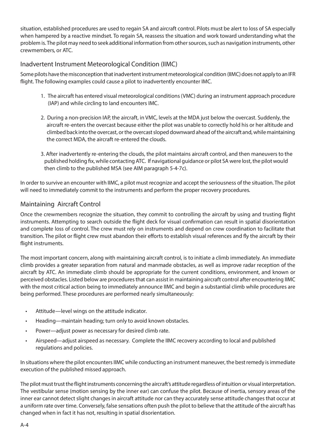paragraph 547C. In order to survive an encounter with IMC, a pilot must recognize and accept the seriousness of the situation. The pilot will need to immediately commit to the instruments and perform the proper recovery procedures. Maintaining aircraft control. Once the crew members recognize the situation, they commit to controlling the aircraft by using and trusting flight instruments.